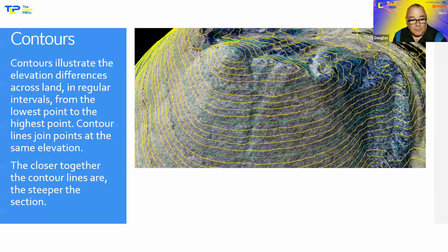Where we're dealing with photogrammetry, we can also output contours. Depending on the camera that's used, resolution may be lesser. We might not be able to get down to 1 foot contours if we're using a low resolution RGB sensor or photogrammetric sensor, but we still can do it. It's the render and output time that's going to cost us a little bit.